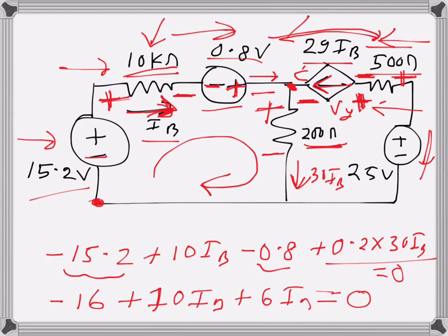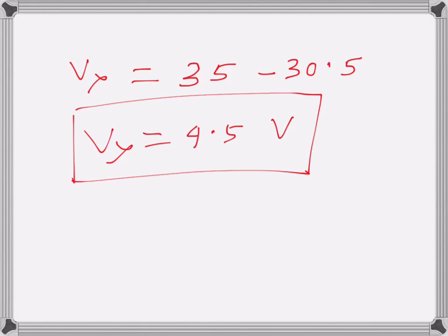What we can see is that in this current source the current direction is in this direction, and the voltage drop is in the direction of the current. So this one is actually dissipating power. We can observe that phenomenon here, and it happens because this is a dependent source, and sometimes even an independent source can dissipate power depending on the connection. We have seen that earlier in some previous problems. So anyway, that's the result here.